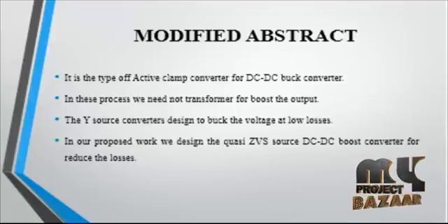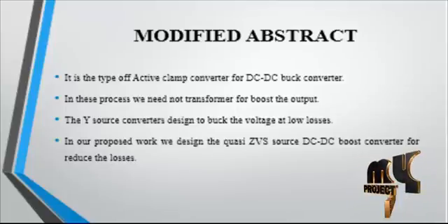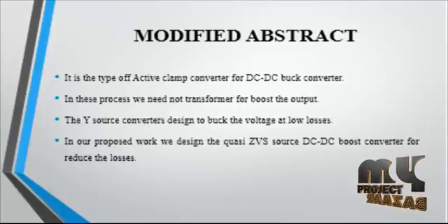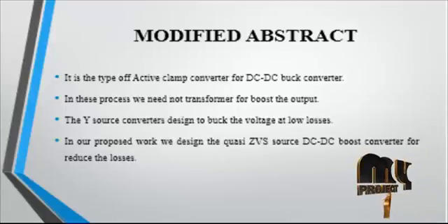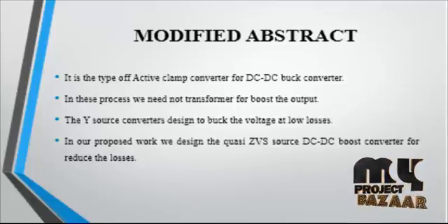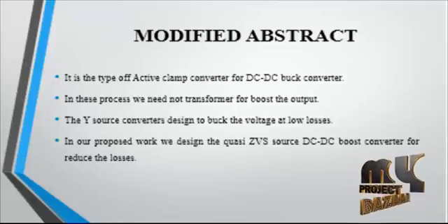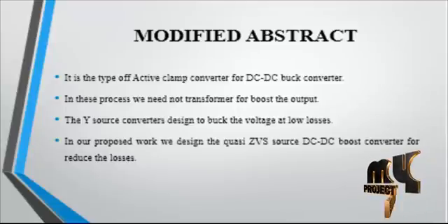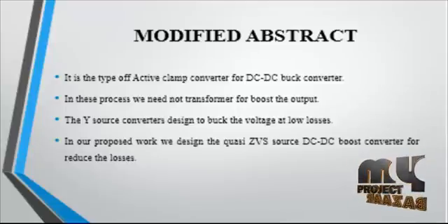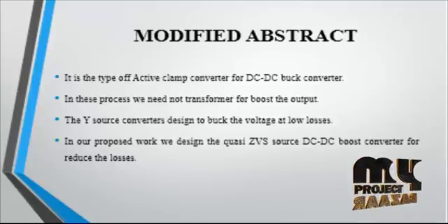Simple expressions for the maximum duty cycle for subharmonic free operation are obtained. A converter circuit proposed to reset the flux in the isolation transformer of a flyback converter developed into a new family of soft transition converters. Such converters are named active clamp converters. The analysis of active clamp converters has been presented with different topologies and different levels of approximation.